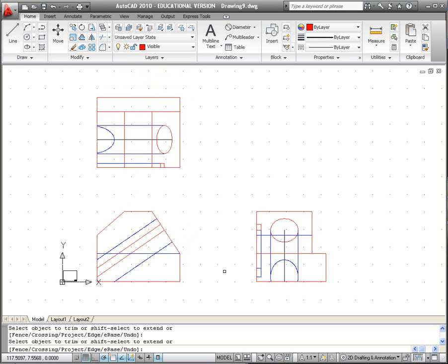Basically, that's the drawing. Now, you may be wondering about the next part. How do we get this whole thing set up correctly? Because there's our printable paper. Well, if you recall, these dimensions that are like 30, 40, 50-ish are millimeters. So sometimes you'll have a metric drawing that you need to scale and put on a piece of paper, and this is one way to do it. There are other ways to do it using layout space, but this is one way, since it really is supposed to be small enough to fit in the title block.